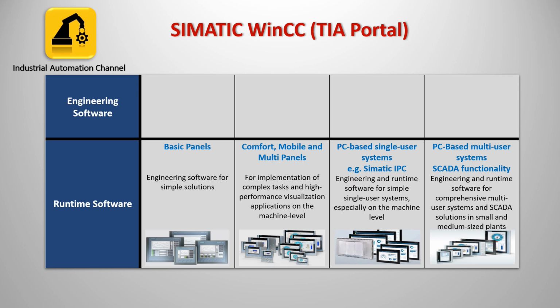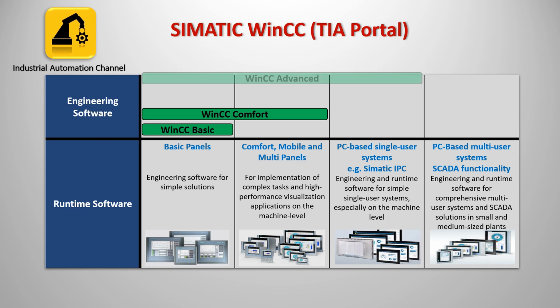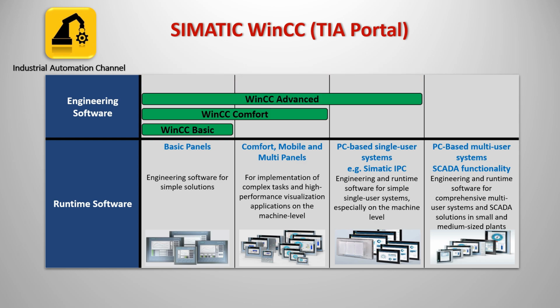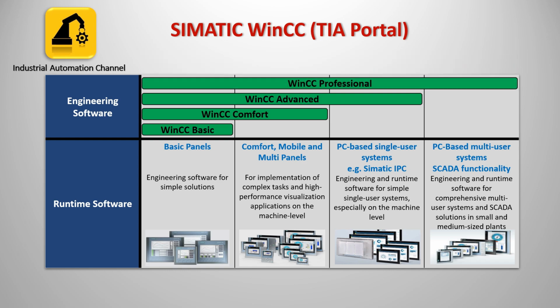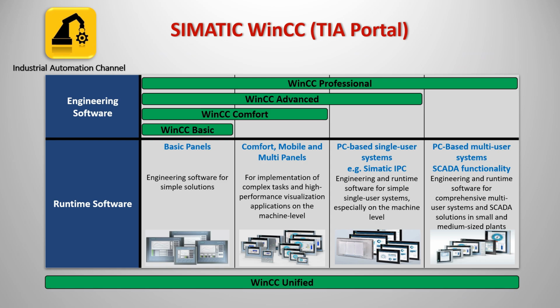Here you see different kinds of Simatic WinCC. Simatic WinCC Basic for simple solutions, optimized to control the basic panels. Comfort for implementation of complex tasks and high-performance visualization applications. Advanced for simple single-user systems, especially on the machine level. Professional for multi-user systems and SCADA solutions in small and medium-sized plants. And Simatic WinCC Unified, the modern visualization system that brings visualization functions to a variety of platforms.